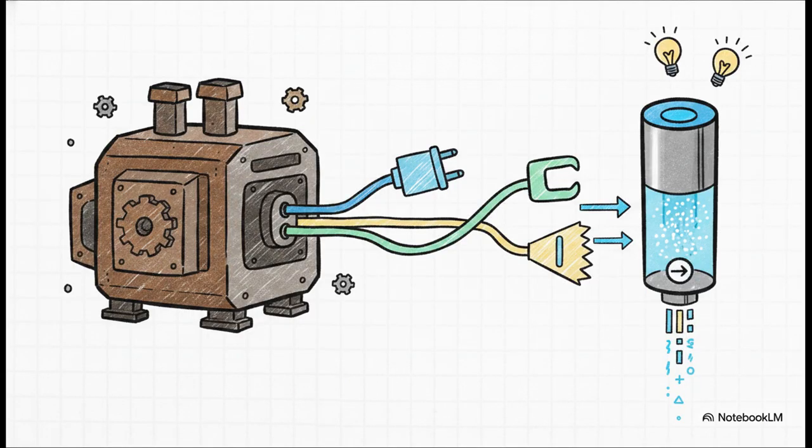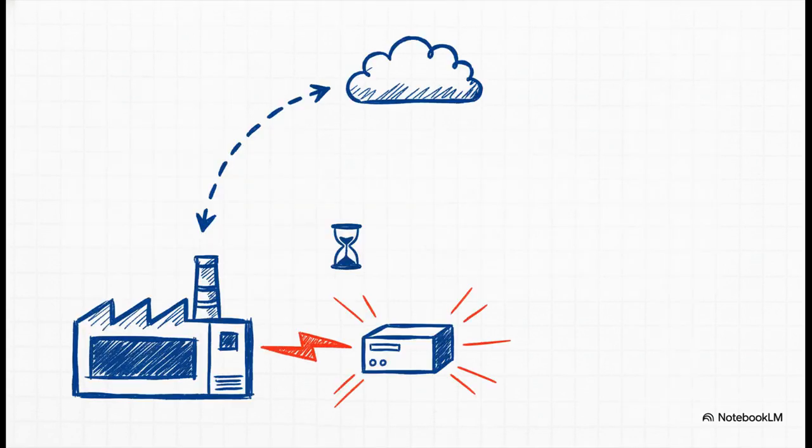Step 1 is OT ingestion. Simply put, you can't run analytics if you can't pull telemetry from your legacy equipment. So we use standard ingestion protocols to connect these 30-year-old brownfield machines. We deploy OPC UA for complex secure data modeling. We use Modbus for older serial devices, and MQTT for lightweight publish-subscribe messaging. These basically act as the universal translators on your factory floor, pulling that raw, continuous telemetry right out of your aging assets. But here's the catch.